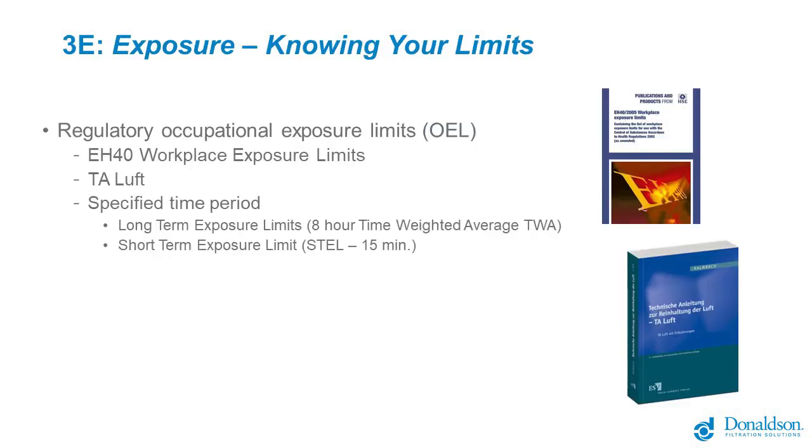There are different regulatory requirements for different parts of the world, and clearly performance of the LEV system needs to satisfy local requirements. A contaminant usually has an official published indicative occupational exposure level, which is based on the severity of the hazard and set to protect the health of workers. Occupational exposure levels is given as a concentration in clean air averaged over a specified period of time, referred to as a time-weighted average. 2 time periods are generally used: long-term exposure limit over an 8-hour period and short-term exposure limit over a 15-minute period. Details can be found in official documents. 2 examples are EH40 workplace exposure limits in the UK and TA Luft in Germany, and similar documents exist for other countries.